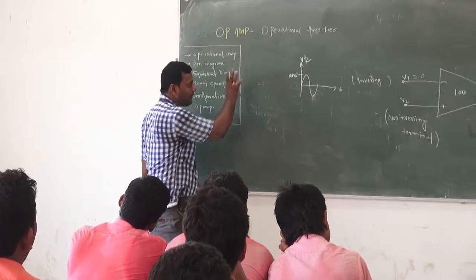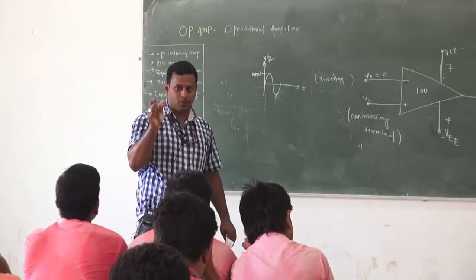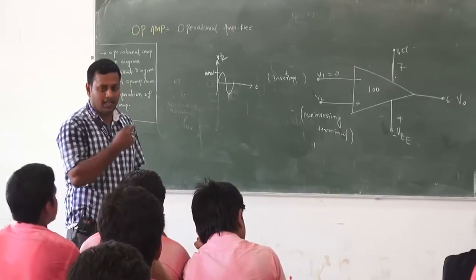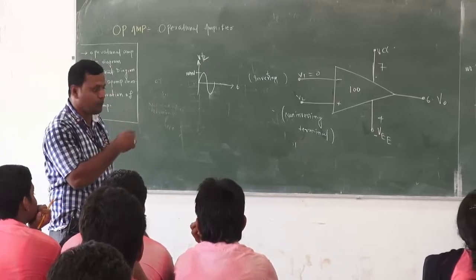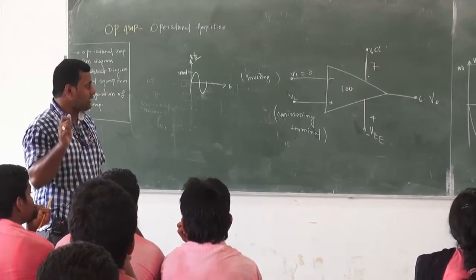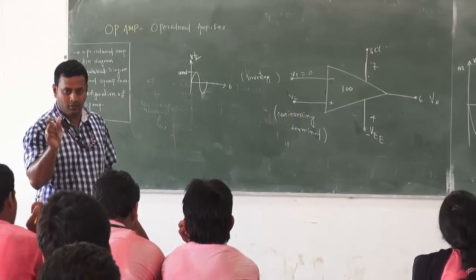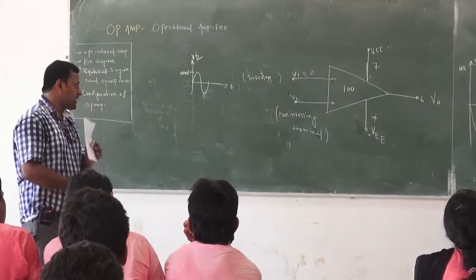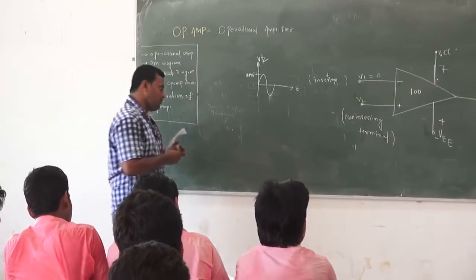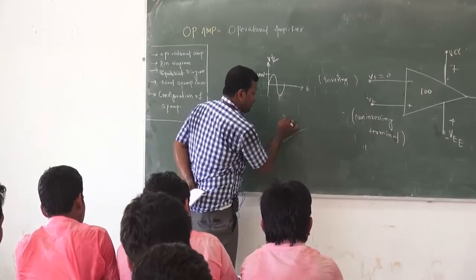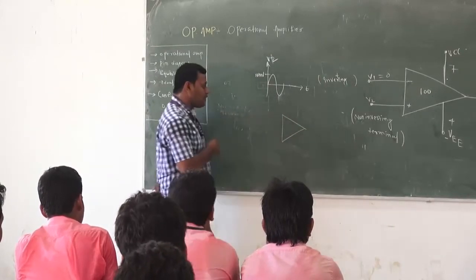So there is the pin diagram. In the pin diagram, I only have to explain the inverting and non-inverting pins; the output, and pins 4 and 7, all of you know. Then there is another, the offset null, I think pin 1. So the offset null, actually, is from the specification point of view.